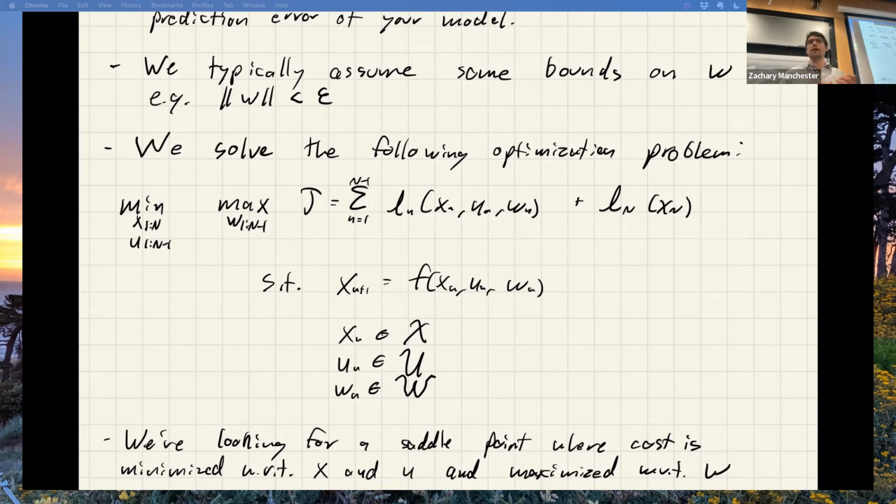And what you're really doing, if you want to think about it, is getting a parametric solution to this problem. When I solve LQR, I get a feedback policy that's a function of X. So you're getting a parametric solution to this minimization problem where for any given X, I can plug it into the policy and get the optimal XU trajectory, right? Does that make sense? So it's a very clever, cool dynamic programming control theory thing. Ultimately, you are minimizing with respect to both X and U, but there's this very nice structure in there that lets us solve it with this dynamic programming trick and get this nice result.